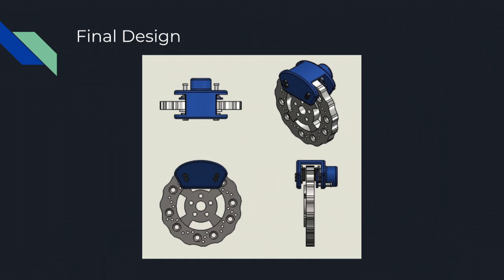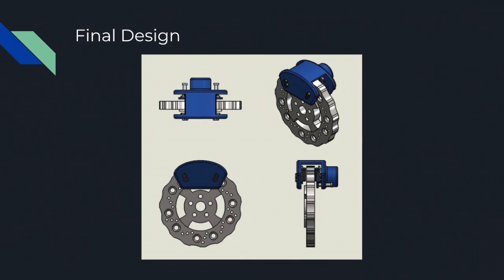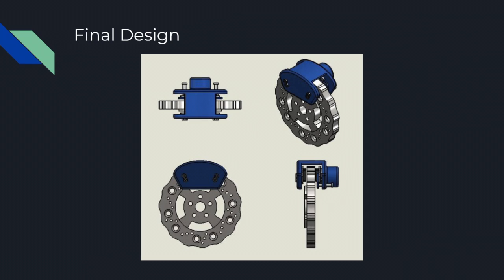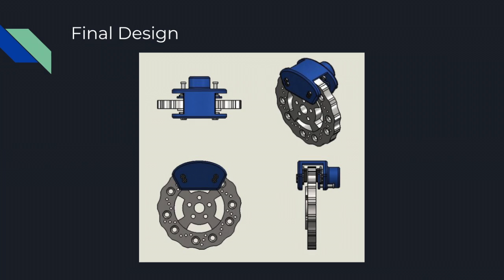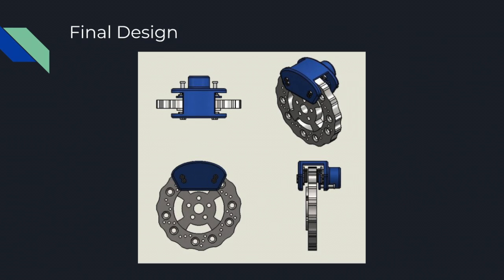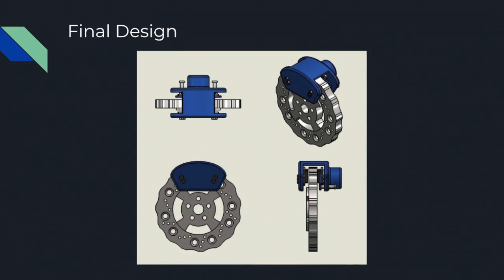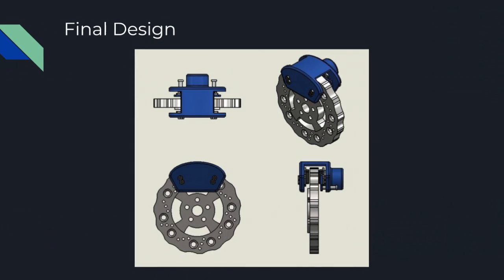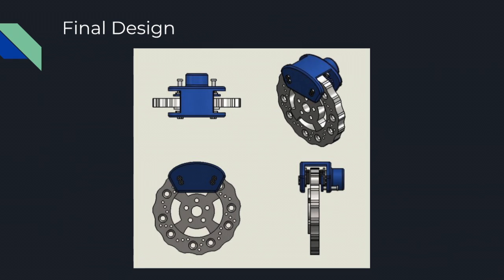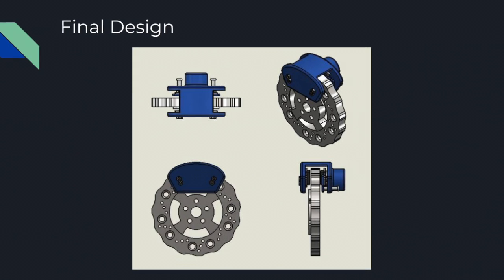Final design. This is a photo of our final design in the orthogonal view. We modified the rotor thickness to 1 inch from an initial 0.5 inches. We also updated the caliper width to adjust for this change. These changes made our design safer and increased the factor of safety from 57 to 60 under static loading conditions.